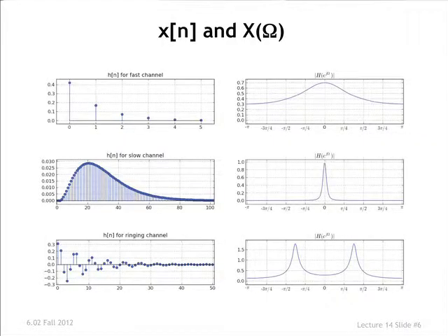Is that roughly consistent with what we're seeing there? Does the spectral content drop off? Well, here's pi over 4, here's pi over 8. Somewhere around pi over 9, we've run out of underlying components, right? It's because the frequency content is limited to that range that the associated signal doesn't wiggle any faster than this. All right?